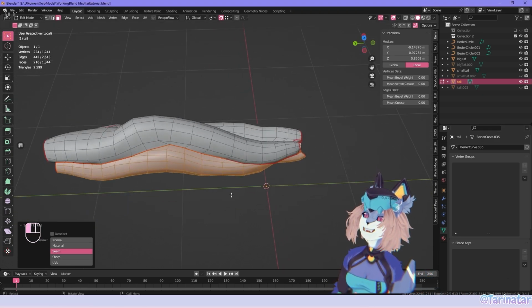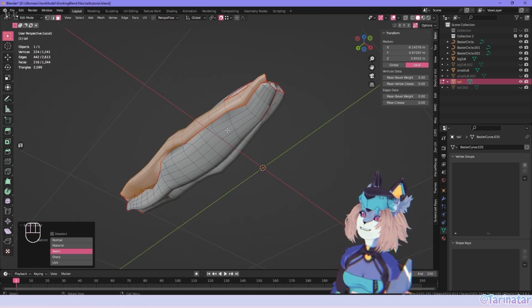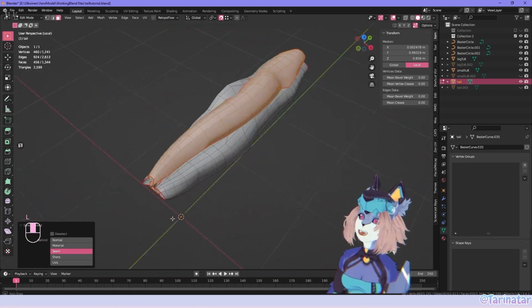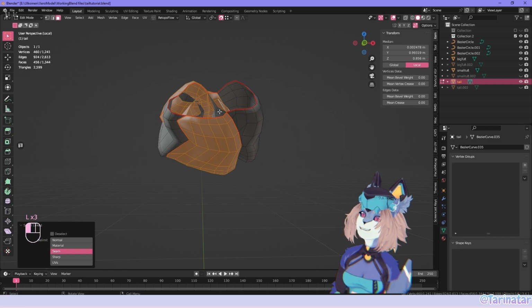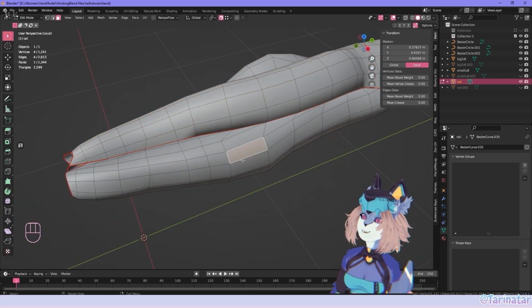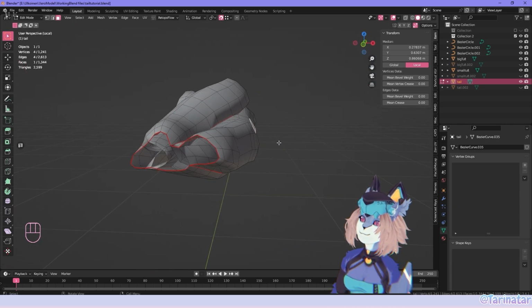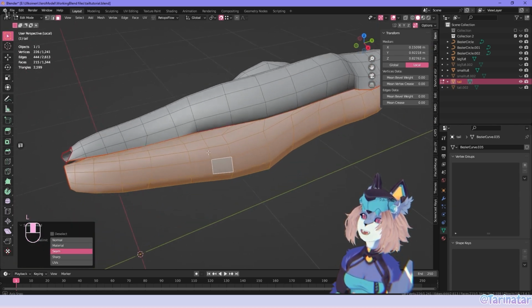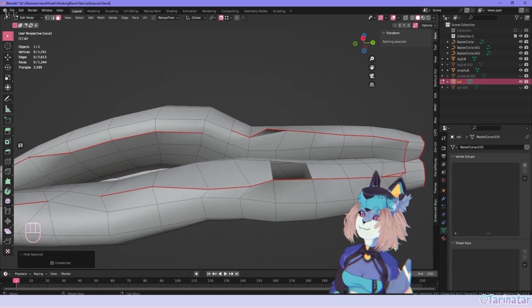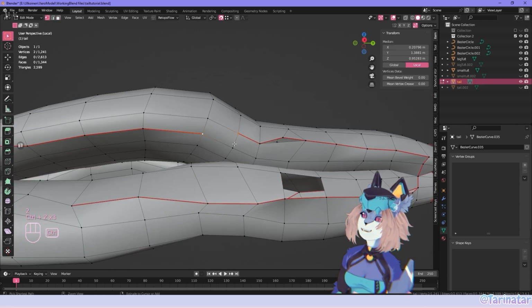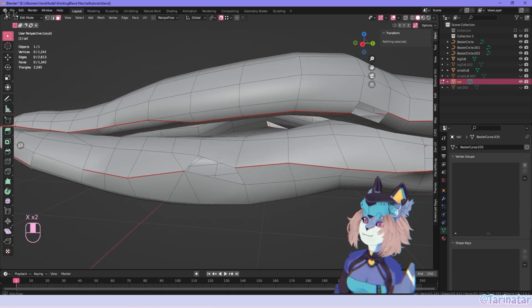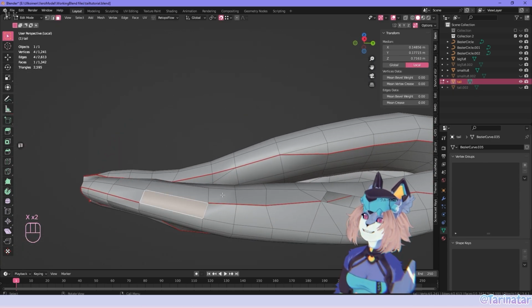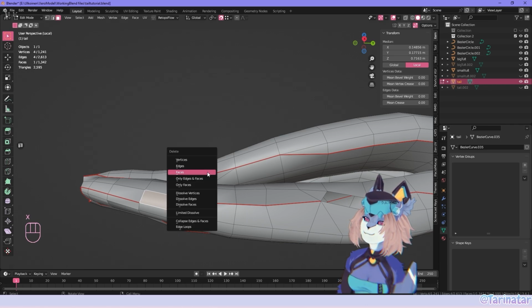Now that we've done all the outside parts, you notice that all of these, even if I do my best, the insides do get selected with link select. So we need to start cleaning up the seams from the inside, and we do that by hiding parts. Like there. We can easily spot these. And we can actually delete that face for now. Delete the faces where it is clear that the cut goes between these.